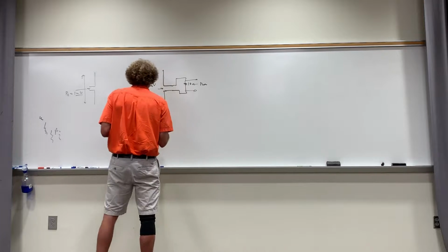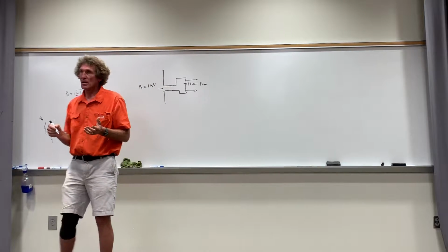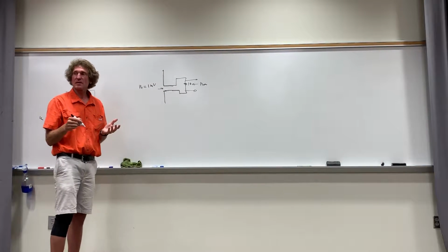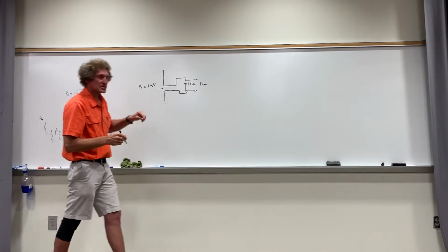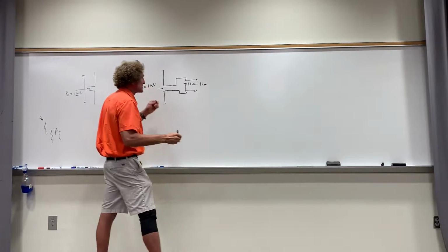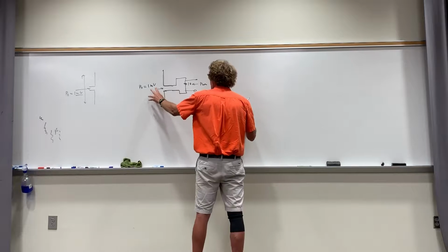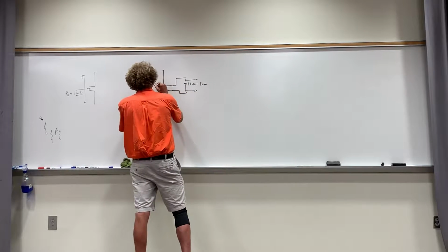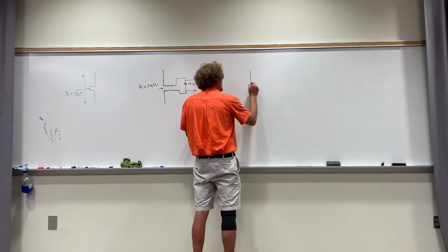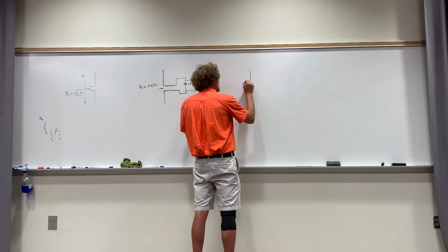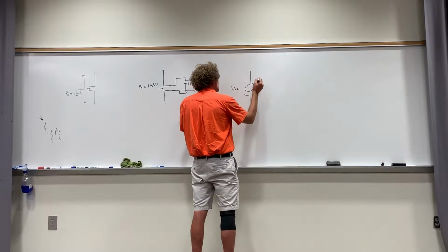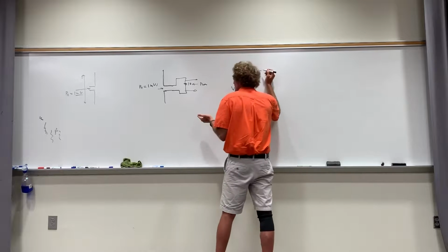So first, you have to take a look at how, in the last lecture we did this too, how we model this antenna. When power is coming into this antenna, and you're receiving 1 milliwatt, what it's assumed is that there's some theoretical open circuit voltage that we can actually calculate. And then there's the antenna impedance.